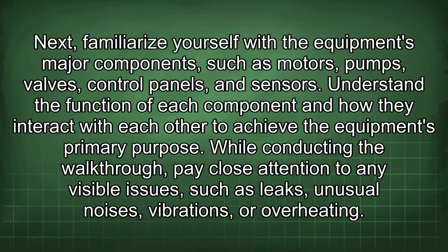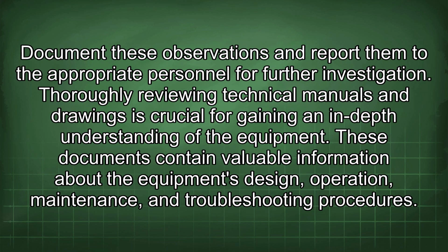While conducting the walkthrough, pay close attention to any visible issues such as leaks, unusual noises, vibrations, or overheating. Document these observations and report them to the appropriate personnel for further investigation.